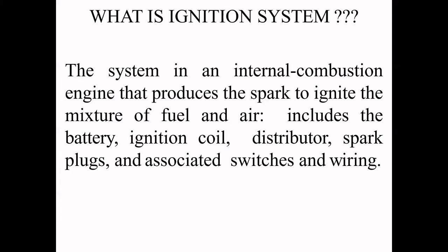Now coming to the ignition system. Generally, we have two types of engines: one is the petrol engine, one is the diesel engine. The petrol engine is called the spark ignition engine. The diesel engine is called the compression ignition engine. In a spark ignition engine or petrol engine, the ignition of the fuel will take place at the end of the compression stroke.